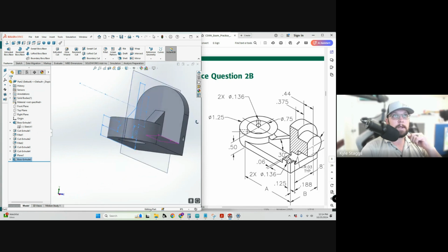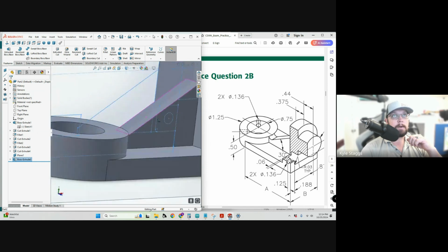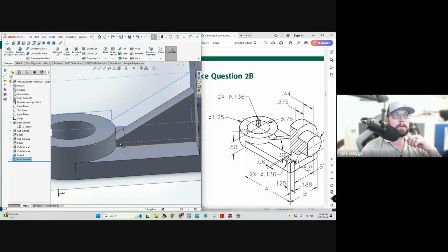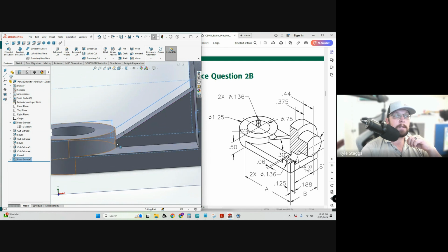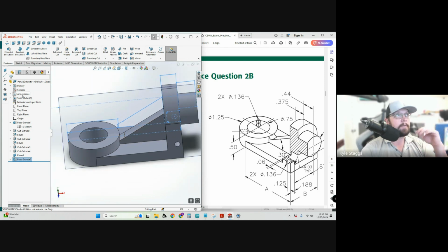Again, that step won't be immediately clear exactly to all of you. To clarify, what I've done there is created an additional piece that goes inside this geometry to avoid the zero thickness conflict that inevitably comes up, so that I can then do a fillet and get it as close as I can.